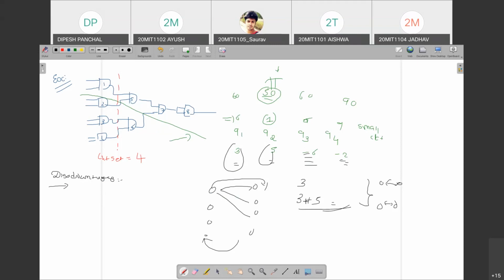So if you see here gain was 5, and if I select only this swapping of 4 and 6, it will result into 6 cut set, which is a large number. So cumulative additions you have to do. You have the starting point, gain 1, that is 3. Second gain is 3 plus 5, which is my 8. So I have to do swapping of 2 pairs, 3 5 also and 4 6 also. That results into only 1 cut set instead of 6.